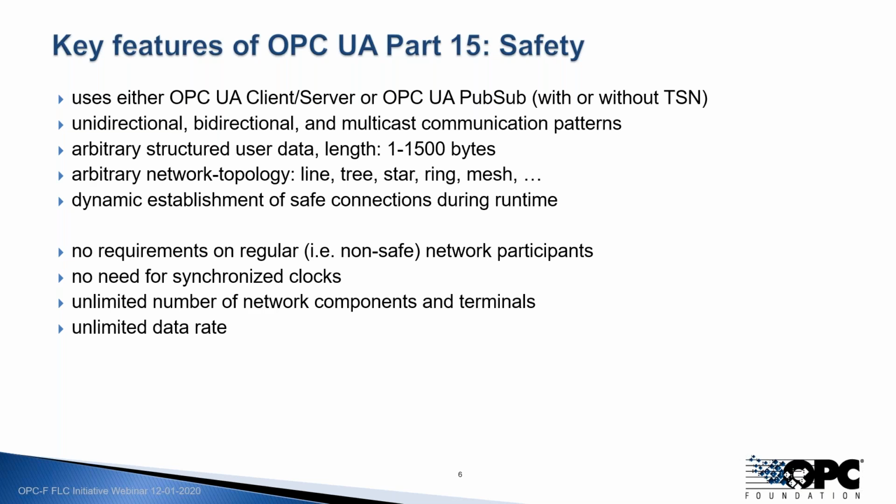And the answer is, from a safety point of view, there are no requirements, because OPC UA safety is able to detect such disturbances. So it will be noticed that there is a problem, and the receivers are going into safe state. Of course, from an availability point of view, that might be a problem, because then all your safety components go into a safe state and your system is no longer operating. But from a safety point of view, there is no requirement here.